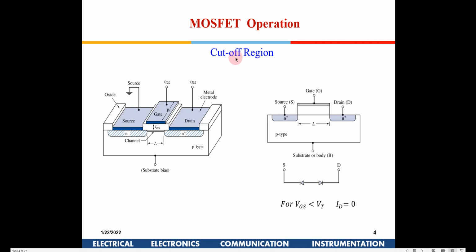Okay, so the MOSFET is generally used as a switch in digital VLSI circuits, and since this course is primarily on digital VLSI, we'll focus on MOSFET operation as a switch. Initially, if you see here, how is an N MOSFET made? You have a P substrate into which you have an N source and an N drain, and then they are separated by a P channel, whose extent is known as the length of the channel. Over the channel you have an insulator, which is TOX.